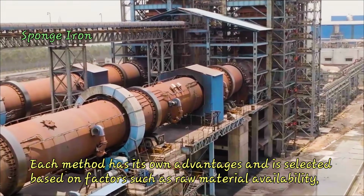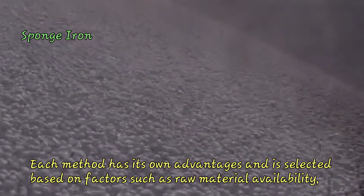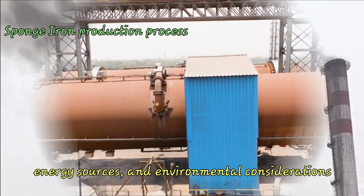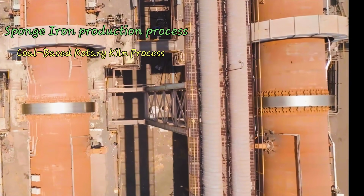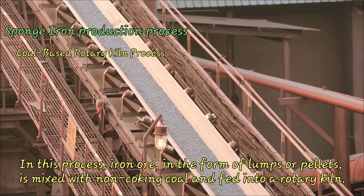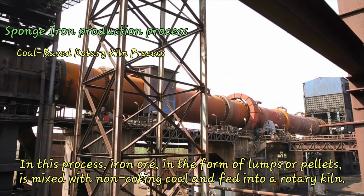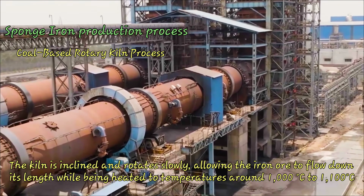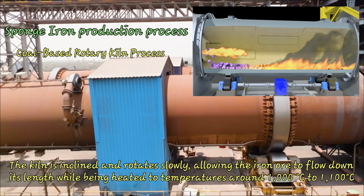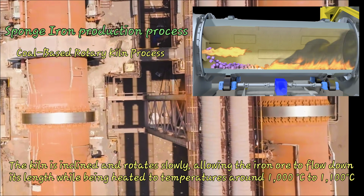Each method has its own advantages and is selected based on factors such as raw material availability, energy sources, and environmental considerations. Coal-based rotary kiln process. In this process, iron ore, in the form of lumps or pellets, is mixed with non-coking coal and fed into a rotary kiln. The kiln is inclined and rotates slowly, allowing the iron ore to flow down its length while being heated to temperatures around 1000 degrees Celsius to 1100 degrees Celsius.